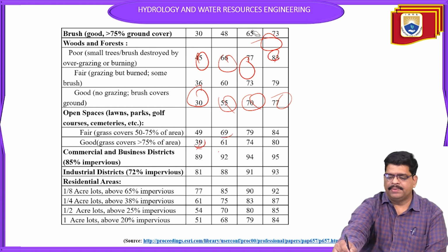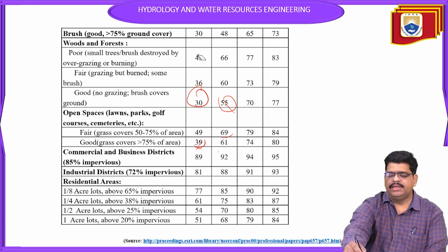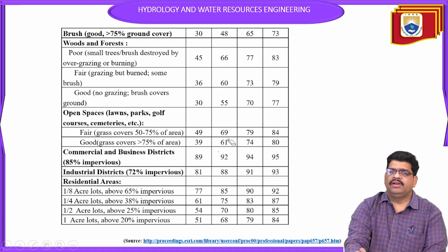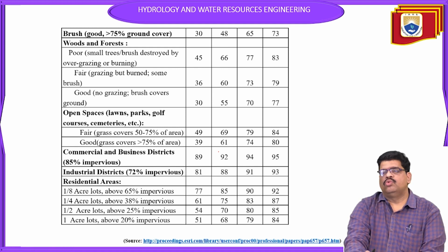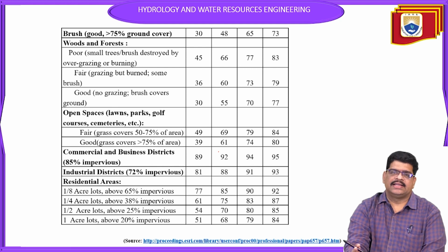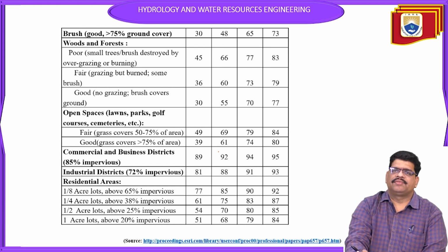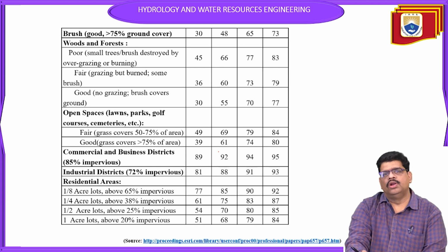These values, by using this curve, we have to calculate as previously. The curve number values can be directly taken, and also we can calculate the runoff. That is very important, the ABCD soil bifurcation. We have to find the curve number easily from this table.